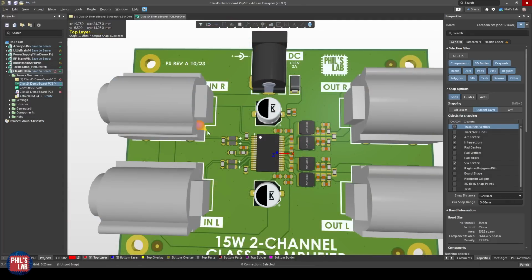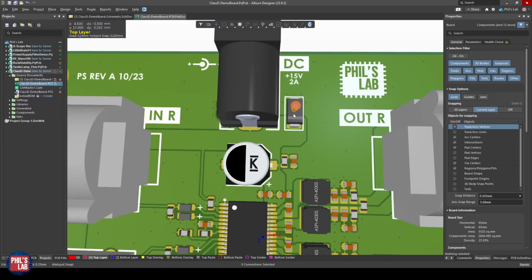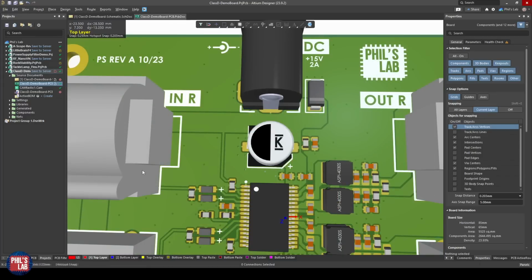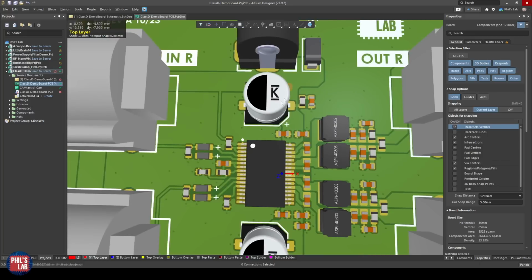After we've looked at the AC input signals, we also have to consider of course our power flow. We come from this DC barrel jack at the top, we have the TVS diode if we want to place it or not, close to our input connector, and we use wide polygon pours, wide enough to handle the current requirements without any ambient temperature rise, that feed into the IC via our bypass and decoupling capacitors.